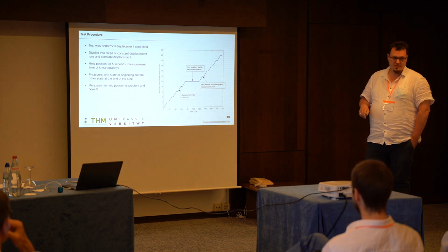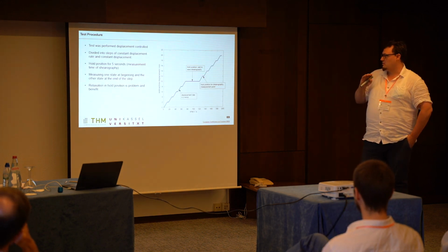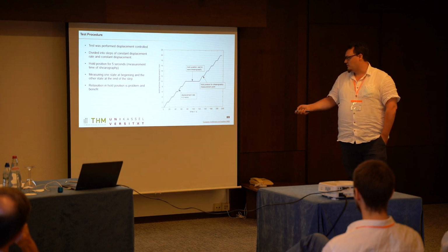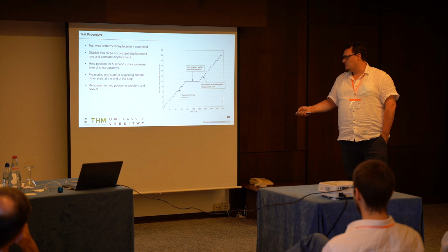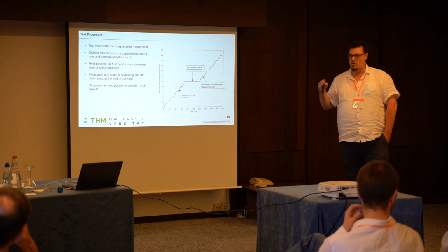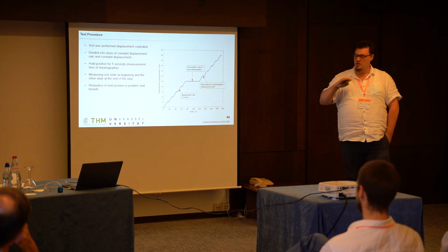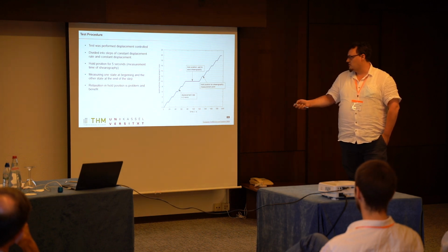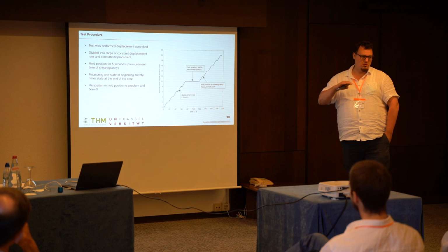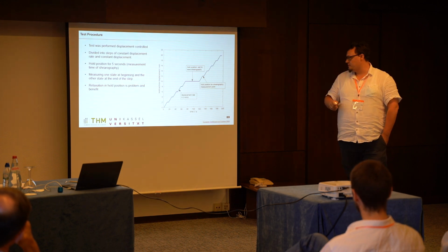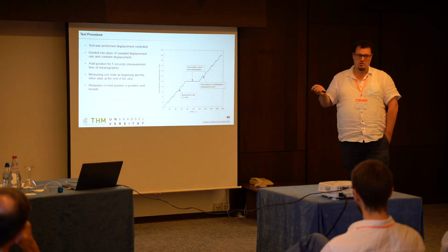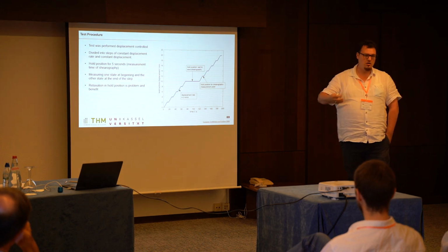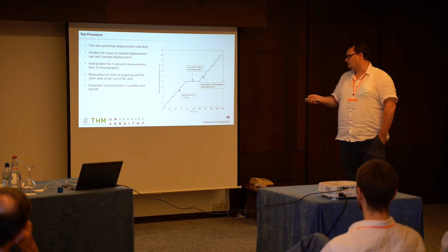Now some words about the test procedure. The test was performed displacement controlled. We started with a constant displacement rate. After this we hold the position for 5 seconds, then we load again. In the middle you see here a larger area where we hold the position for a longer time period. This is caused by saving the data from the shearography system, and then we can start loading again.